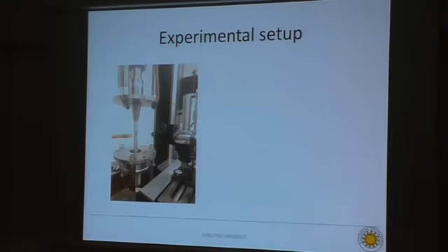Experimental setups, just so we can see how our setups look like. We can see the ultrasonic fatigue testing machine with the horn and oscillator up here. Here we have our specimen, and here we have a camera pointing at this plane surface in the middle, where the camera is connected to a computer software where we can measure the crack length. And we are also using cooled air to cool the specimen while testing.